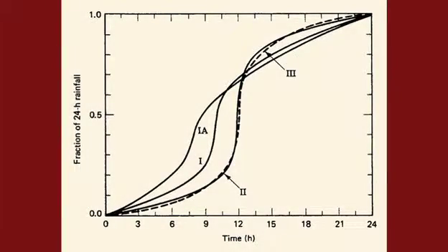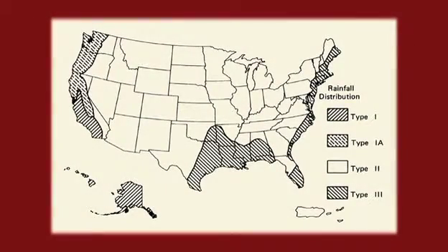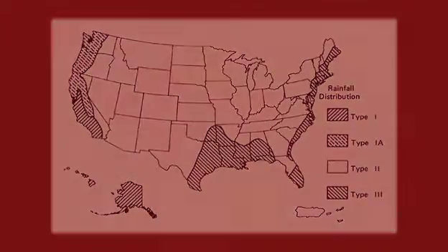Rainfall is described in terms of total rainfall depth in one of 4 standard 24-hour temporal rainfall distributions: Type 1, Type 1A, Type 2, and Type 3. These rainfall distributions are applicable in the United States as shown here. The duration of 24 hours was selected because most rainfall data is reported on a 24-hour basis. Rainfall intensities for shorter durations are contained within the 24-hour distributions.